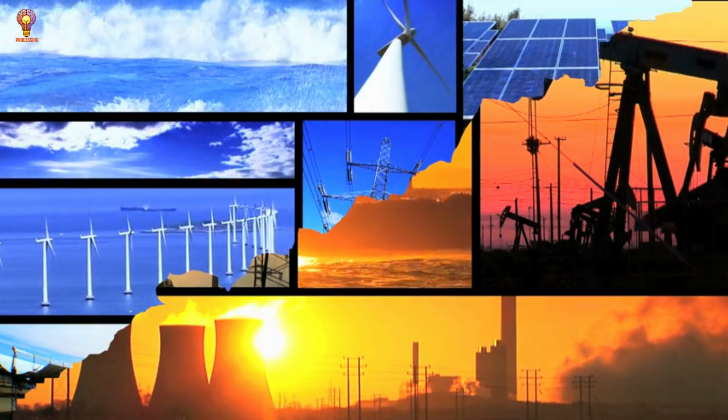2. Nuclear power plants. Nuclear power plants operate similarly to thermal plants but use nuclear fission instead of burning fossil fuels. Step-by-step process. Nuclear fission reaction: uranium or plutonium fuel rods undergo fission, releasing a large amount of heat. This heat is used to boil water and produce steam. Steam drives the turbine: like in thermal plants, the high-pressure steam drives a turbine connected to a generator. Cooling system: the used steam is cooled and condensed in a cooling tower before being reused. A cooling system ensures that the reactor remains at a safe operating temperature. Electricity transmission: the generator produces electricity, which is sent to transformers for distribution.